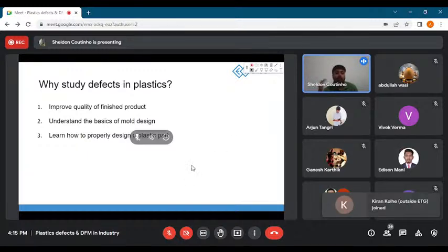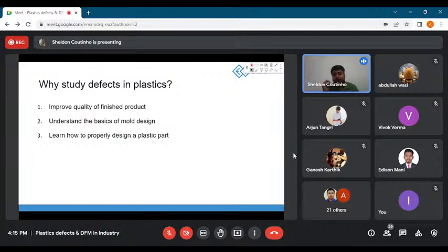Anything can be done in the virtual world, but when you start getting things into the real world for real world applications, it becomes very, very critical to understand that I need to ensure that everything is manufacturable. Things do not fail. If I'm designing something that has multiple parts, say 10 or 20 parts that need to fit into each other, I need to even take into account design for assembly at that point.